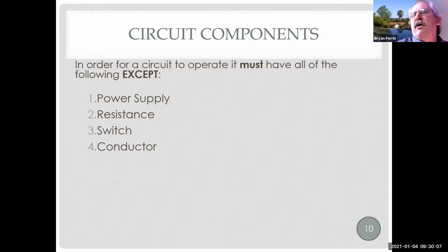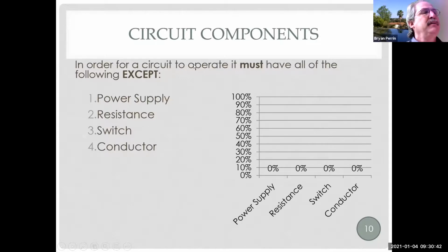Absolutely. And even wire, I have a meter that's sensitive enough I can tell you the difference in resistance between a large wire and a small wire that are both the same length. So if I get down to that engineering level, everything has some resistance. We have an acceptable amount of resistance in our wiring, switches, and things like that designed into the circuit. And then we have unacceptable amounts of resistance that create a problem. So that's the difference between absolute, because you are absolutely right, and functionally correct.